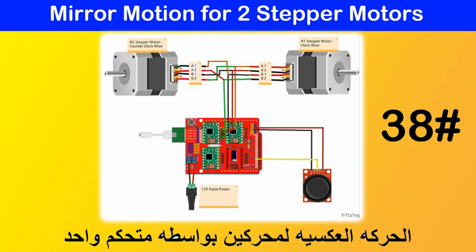4. Common universal motor driver components. Universal motor drivers are often built using the following components. Triac/thyristor, used in AC applications for controlling the power fed to the motor. MOSFETs, commonly used in DC motor drivers and for switching the voltage in a PWM-controlled system. PWM controller, a key component for adjusting the average voltage in a DC motor drive. Operational amplifiers, used in feedback control systems to regulate speed or current. Current sensing circuit, to detect overcurrent situations and provide protection.